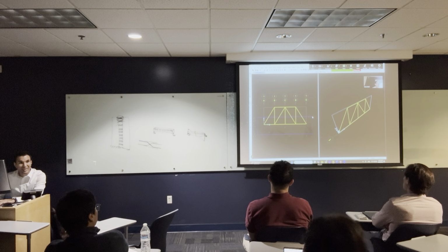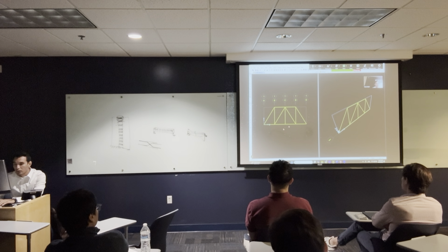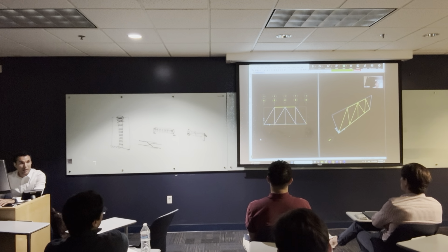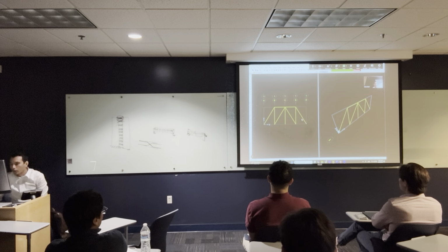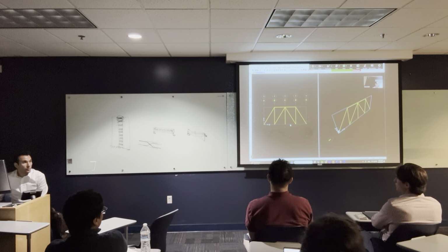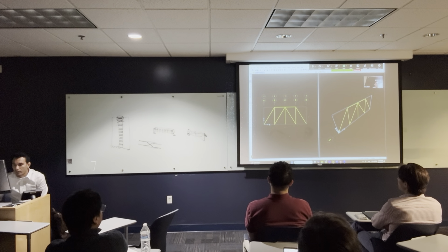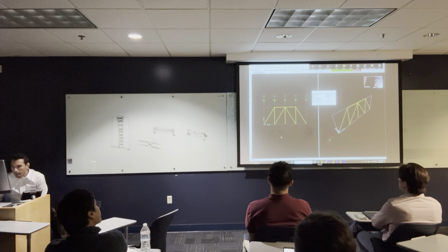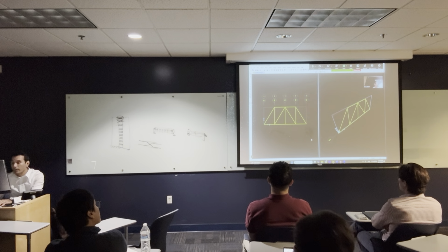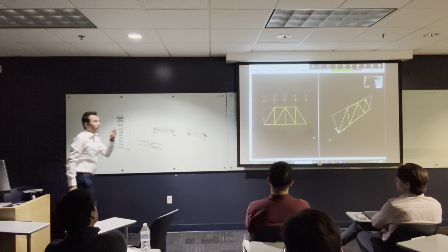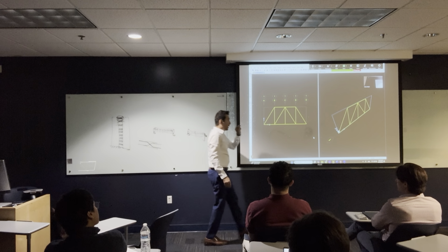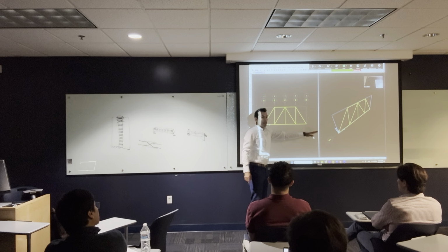Here, it selected everything that is complete. This one selects everything that is touching. And that's a really, really important tool. Sometimes I want to delete these members, so I just deleted these members. And if I want to draw them again, I can draw them one piece at a time, like this. However, drawing them that way is going to make an error down the stream, but we are going to learn from this error.